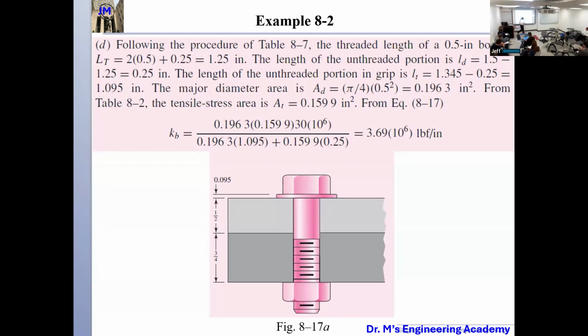And then use this trigonometry. If I know this length, and I know the 30 degree angle, I can know my bottom line. So this is the top line. My bottom line length is determined by the 30 degree angle. With the thickness given, I can calculate this capital D. So this capital D is used for the second frustum.